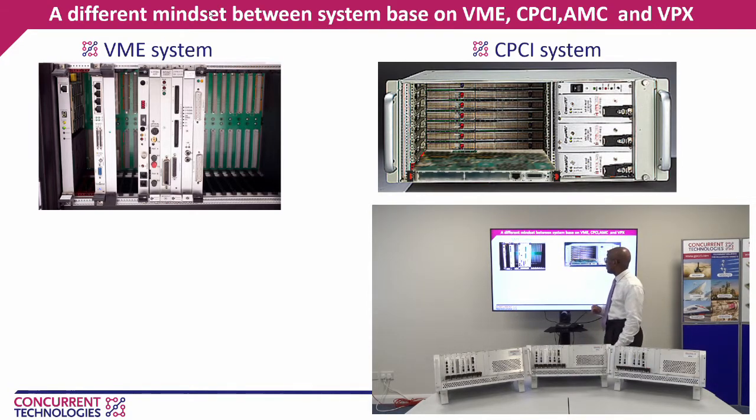Another example of legacy technology, still going strong though, including VME, is Compact PCI. With Compact PCI, there was one thing that you needed to know, and it was very easy to remember because one of the slots was marked in red, which is the slot where you plug your system controller, which initializes your peripheral card, but that's all you needed to remember. You could plug any peripheral card pretty much in any slot, and it will just work.